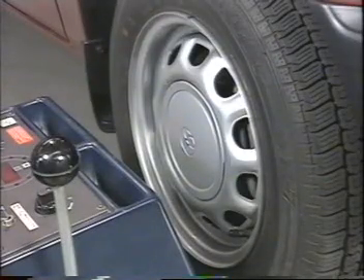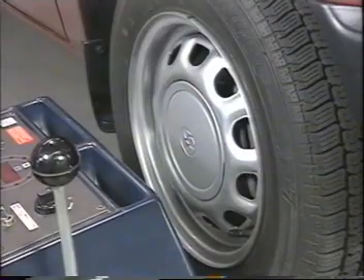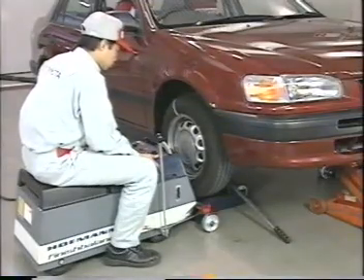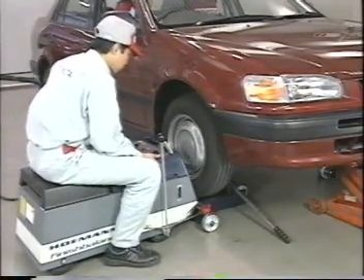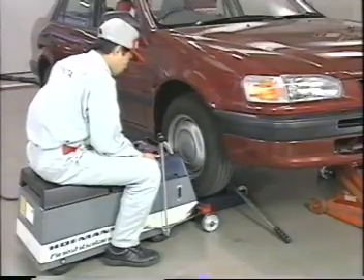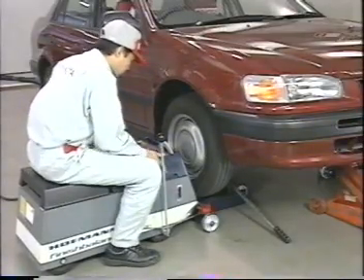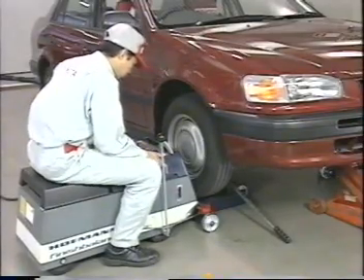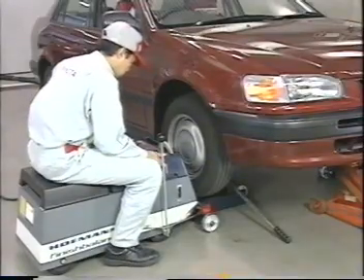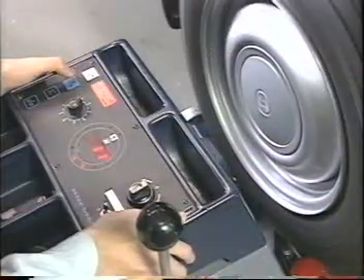On-car balance is checked with the wheel cap, valve cap, and center ornament attached. When correcting the balance of the drive wheels, turn the wheels with the engine started while increasing or decreasing the speed gradually. When the inspection and adjustment of each tire are finished, be sure to check the wheel alignment.